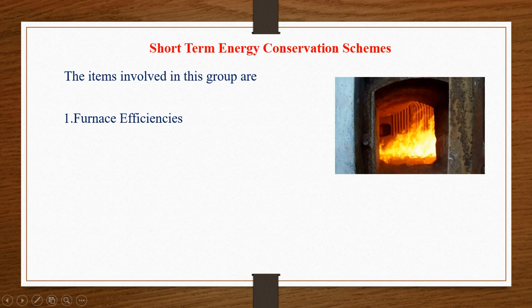But we have to use that heat energy completely to boil the water. That is our aim in the thermal power plant. So we should not waste that heat energy. A highly efficient furnace means it doesn't contain any leaks or cracks or openings. Whatever heat energy is generated in the furnace is completely utilized by the boiler. That's why the furnace must have a good efficiency.